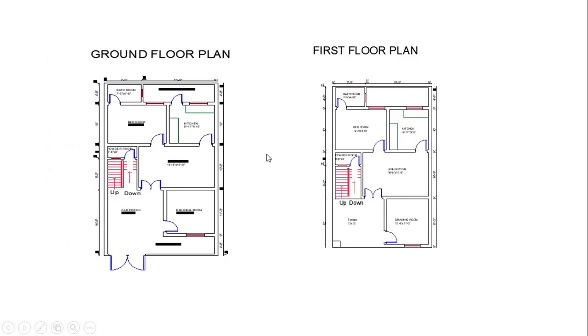And if we go ahead a little bit, as you can see, this is a 5 modular plan, and we have made it in this way. So the first requirement is that you should ensure the privacy of your bedroom. As you can see, if a man is standing there, he cannot see into our bedroom directly. So first of all, you should plan your doors and windows in different ways to ensure the privacy of your bedroom and everything. And the doors must not be parallel to each other.